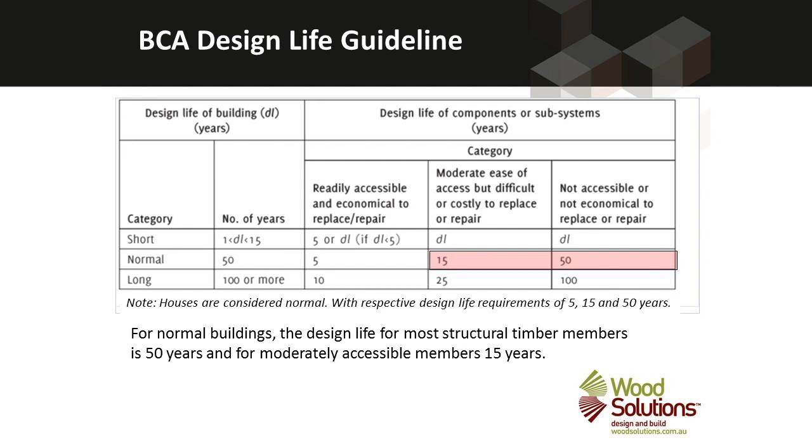So things like plating on the outside of structures or even handrails can be replaced relatively easily. But timber buried deep within a structure can't be replaced relatively easily. In terms of the Building Design Life Guideline, timber that's buried very deep in a structure should be designed for a 50-year life, and timber that can be quite easily replaced should be designed for a 15-year life.